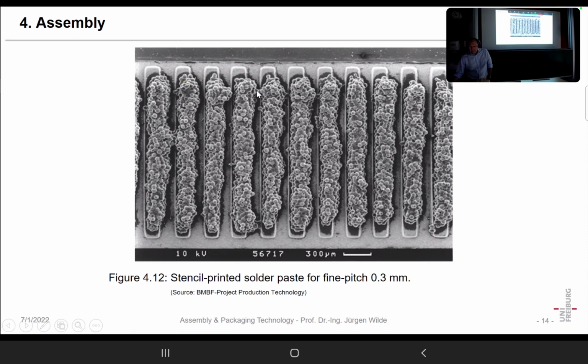And here you have a bridge, and that will also pose big problems. If you made such a mistake on such a device, there is hardly any possibility for rework. For instance, if you resolder it by hand, you bend the leads. So the complete idea of making just finer pitch, if you want to have 500 IOs on a device, was not possible.